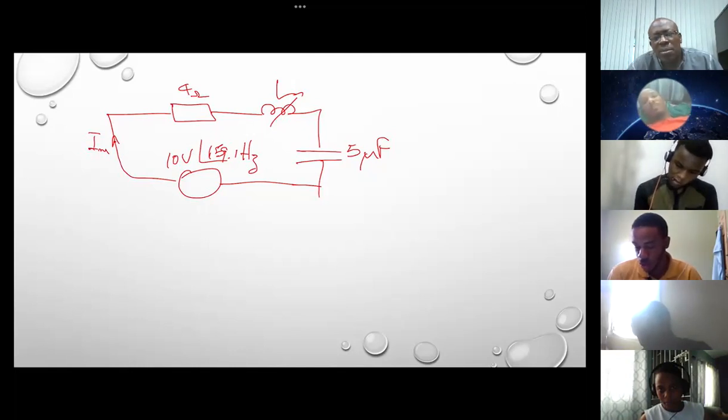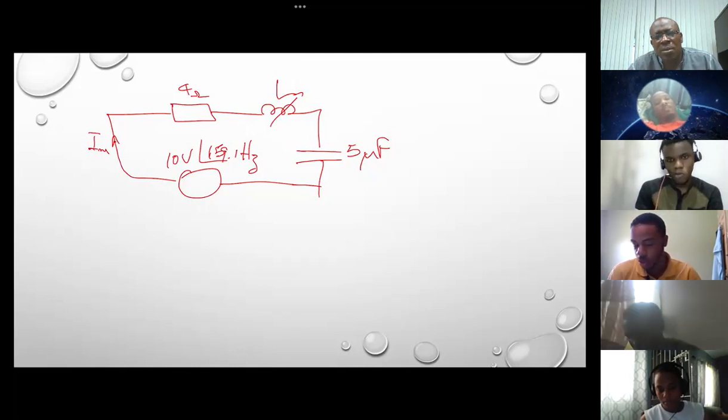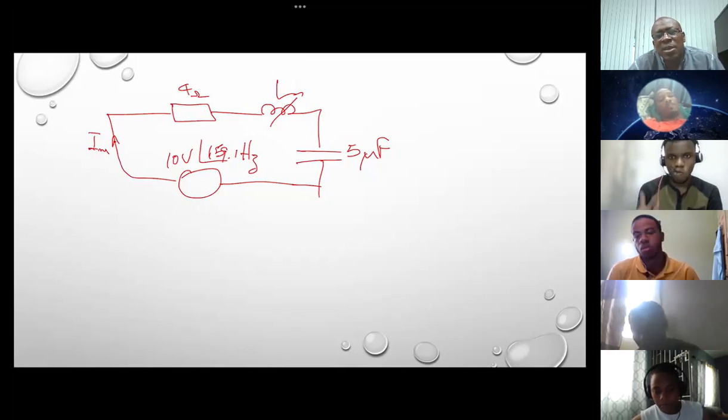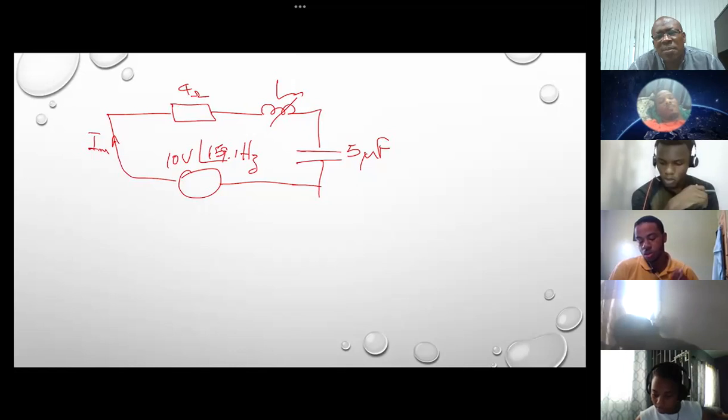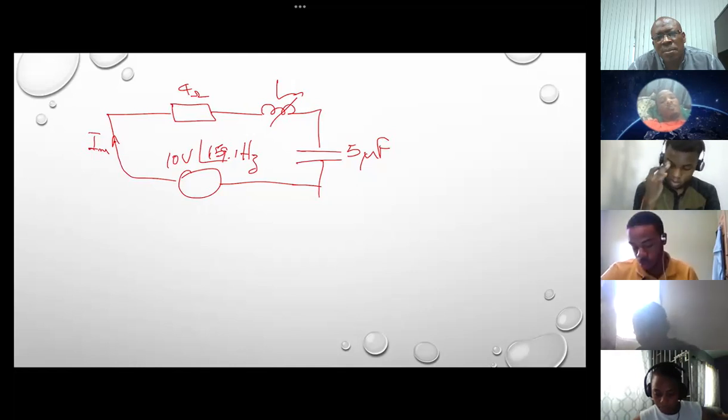Yeah, but isn't there an unknown in that formula? Yes, sir, the inductance, but the inductance should be equal to the capacitance. No. It's the inductive and capacitive reactances which are equal, not L and C. This calculation is wrong.